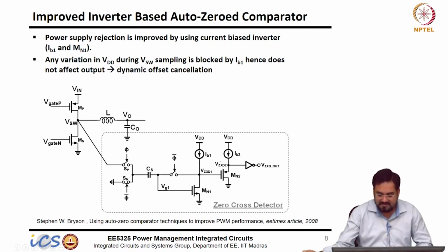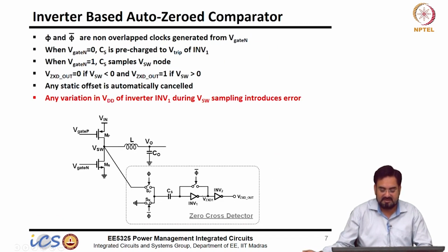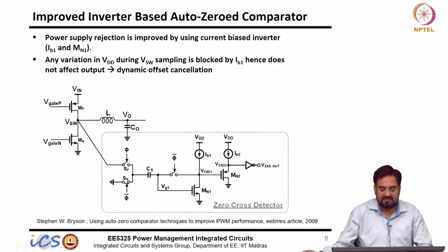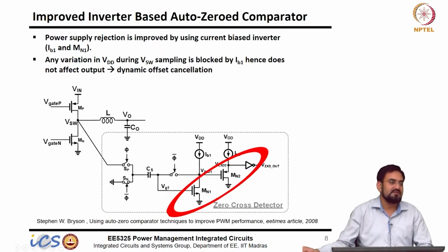No, there is a drawing, this drawing is incorrect, this should be NMOS. Okay. So, anyway, I will fix this. So, you can assume this is NMOS, not a PMOS. And then we need one more inverter, because this is ZX out bar. If you compare with this, we have 2 inverters here, we have 1, 2, 3 inverters here.